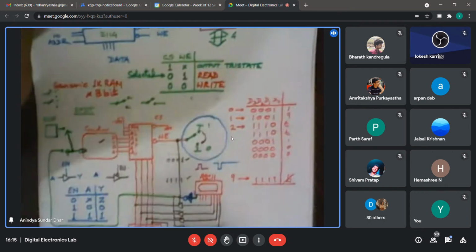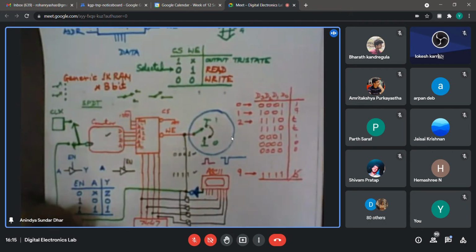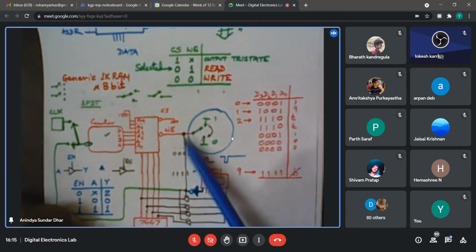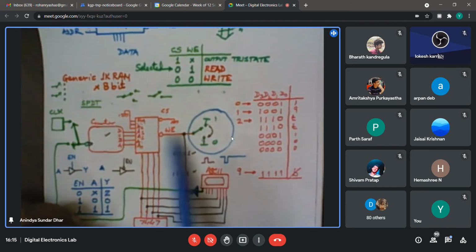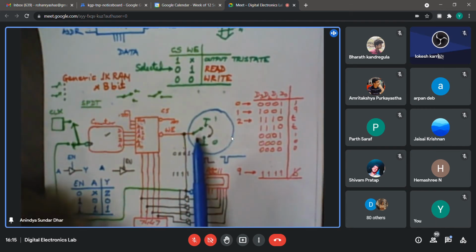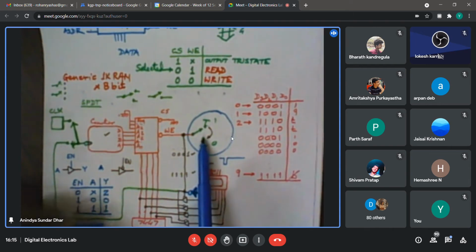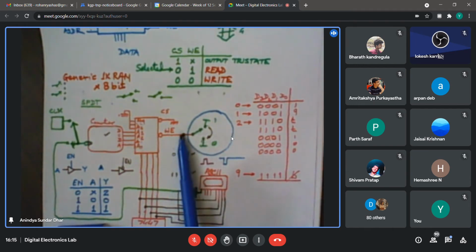Maybe it's not visible. So what I did before drawing this black line, this write enable was just connected to a switch, so that I can control manually whether I want to write or read. Now I said that I can generate this write enable signal from the strobe signal. Here I have actually drawn a single inverter. In lab, a single inverter would work well, but in this case, as I have shown, you require 2 more buffers and an AND gate to widen the pulse.